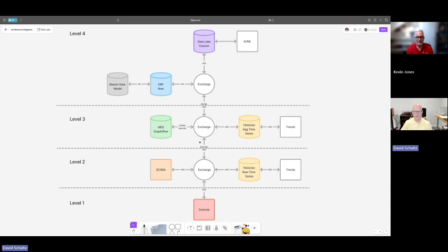Yeah, absolutely. We used to talk about ETL, extract, transform, load, which was very common 10 years ago. I mean, it's still common, but that was really the only way to do it before. Now we have better thoughts around how we want to do these types of things. And that speaks to the power of a unified namespace: the master data model isn't just for the enterprise, it's for everything. It also allows for these exchange mechanisms. If we can do that in an event-driven pub/sub way, MQTT and/or Sparkplug are a quick way to get it. But the point is it's already structured. So when it lands in your data lake, even though it's unstructured data, the more structure we can give it, the faster we can start realizing value with it.